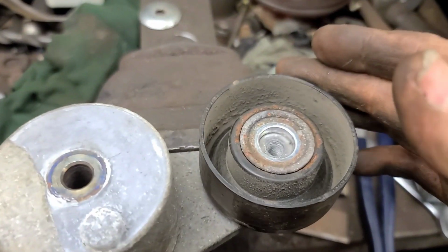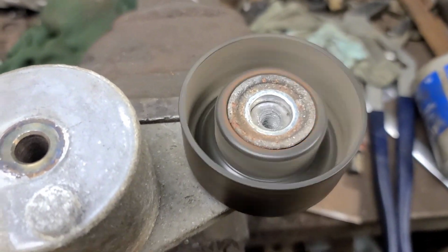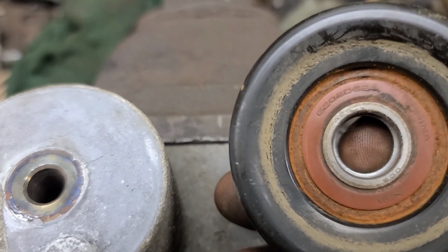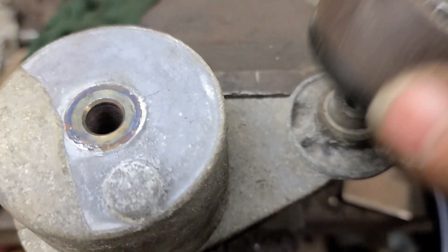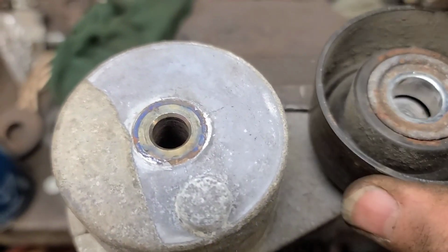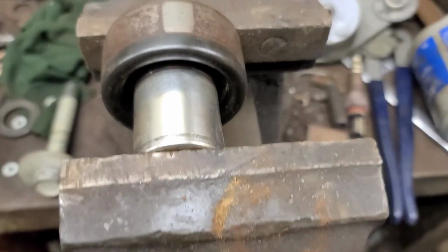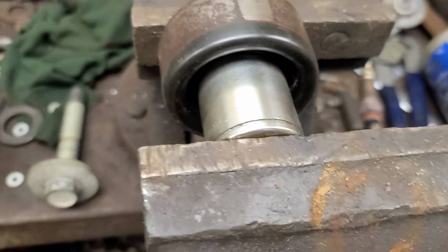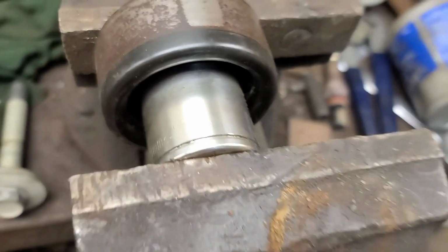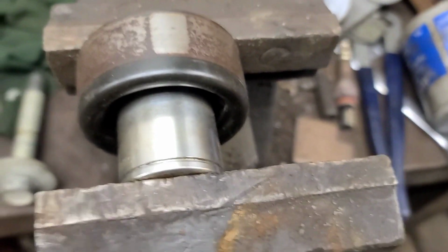and it's a little loud, so I'm going to change just the bearing. It's a 6203 double sealed bearing. I keep those in stock because it's a steel pulley. You can press the bearing out and press a new bearing in. So you can just use a vise and a socket to press the bearing in, as you can see. Not that difficult till it bottoms.